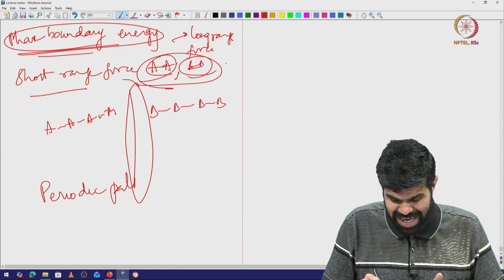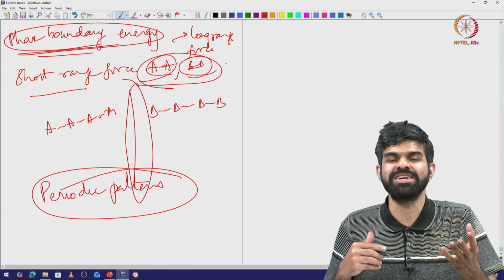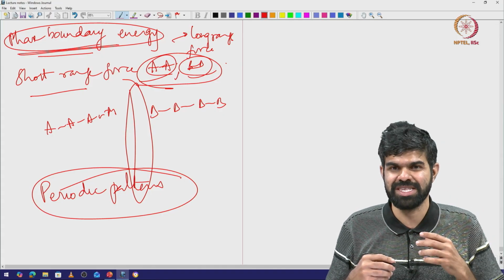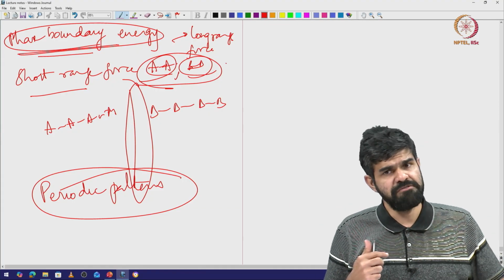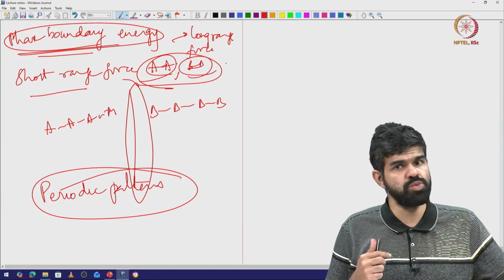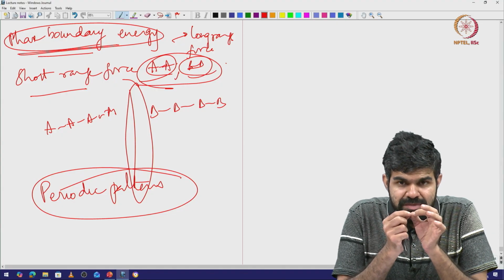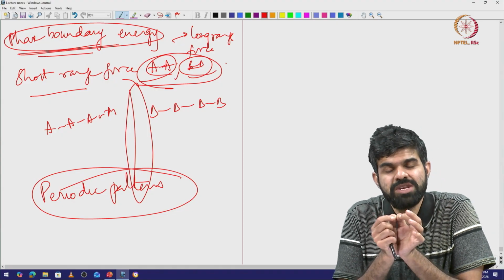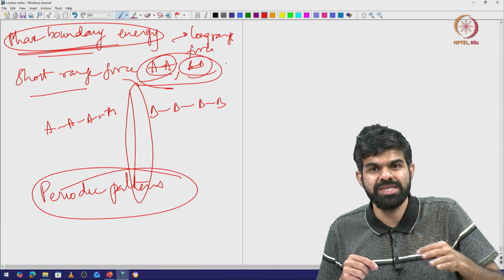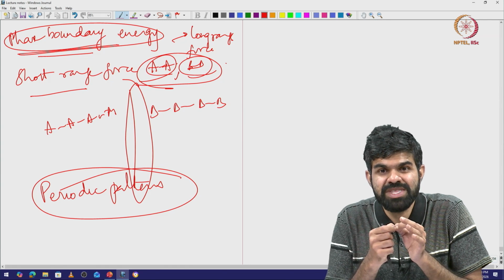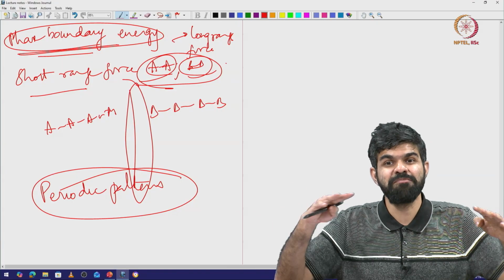So, if you are studying patterns, there is nothing like spinodal decomposition, right. So, I get beautiful patterns that emerge out of various systems. Okay. So, classic example is your sand dunes in desert, right. So, there is a wind force which is a long range force that is trying to move away all my sand particles, okay, and there is this attraction between sand particles. Sand particles want to stay close enough to each other, right. So, that is the short range attraction. Wind is trying to throw away the sand particles, whereas the attractive forces between sand particles want to keep them together. As a result, I get these sand dunes, or some kind of patterns that emerge.